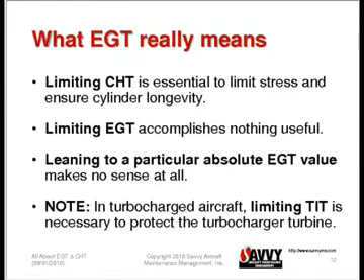But trying to limit EGT, where the probe is right close to the exhaust port and is looking at a very pulsy gas flow, doesn't really make any sense at all, because what the EGT probe is reporting is not a real temperature, and it's not something that it makes sense to try to limit.